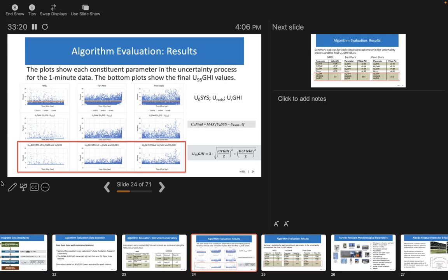Basically, these are thermopile instruments, so you have to have enough photons. Is there a CCD? Is there a photomultiplier tube? No, it's basically a thermopile. It's essentially thermal energy to electrical energy. You have an instrument with photons from every direction, that's on the global. You have this little black detector, and essentially it absorbs all the photons, and then you have the Seebeck effect.